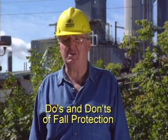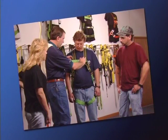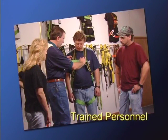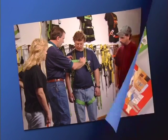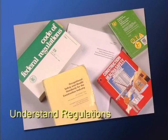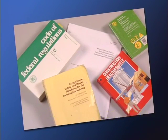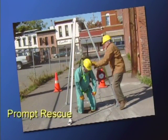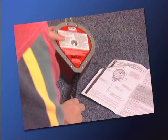As a review, let's explore the do's and don'ts of fall protection. Fall protection equipment should be used only by those individuals who have received training from a competent person. Understand all applicable OSHA, ANSI, and CSA regulations regarding fall protection before using equipment. Employers should provide for prompt rescue should a fall occur. Rescue procedures should be reviewed as part of the company's regular safety training program.